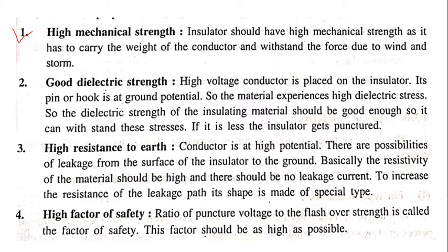Second, good dielectric strength. A high voltage conductor is placed on the insulator, and its pin or hook is at ground potential, so the material experiences high dielectric stress. What is the meaning of this sentence? A high voltage conductor is placed on the insulator, so one point of the insulator is connected to the high voltage conductor and its pin or hook is at ground potential, so the material is going to experience a high dielectric stress, right?